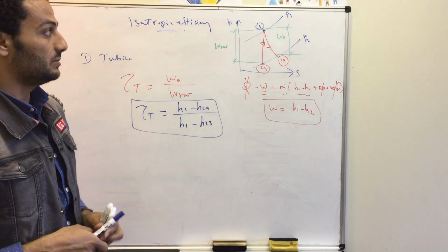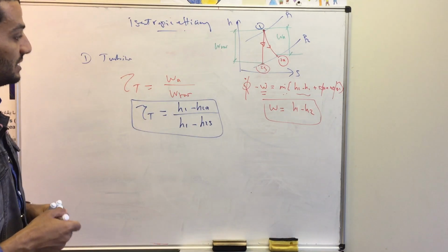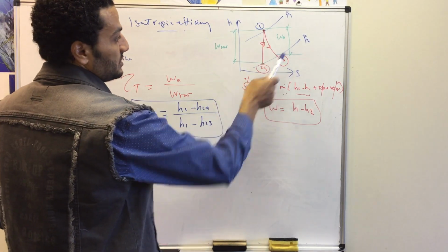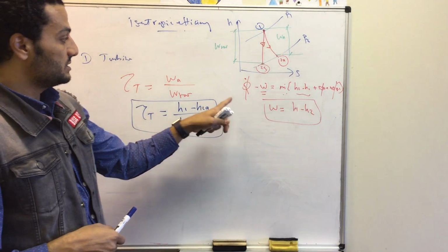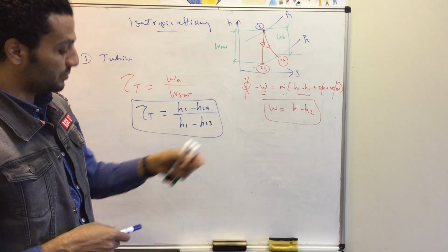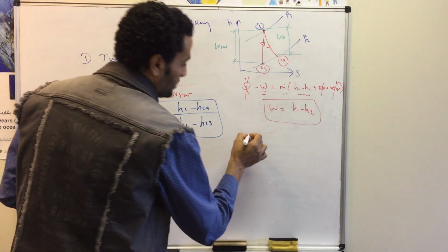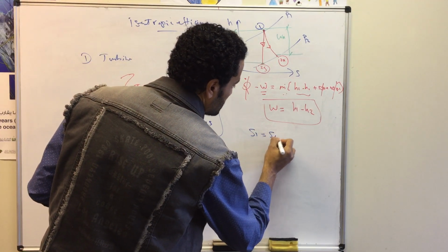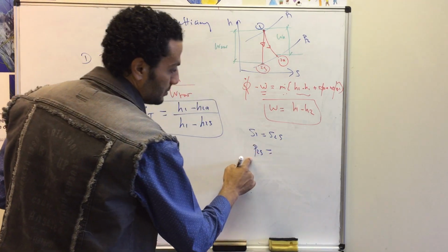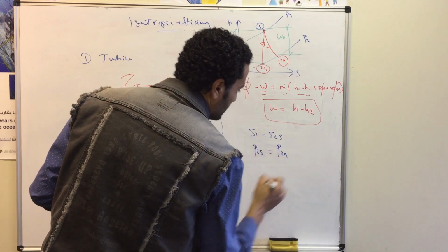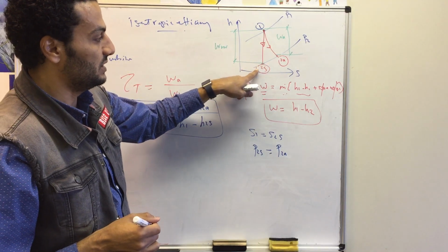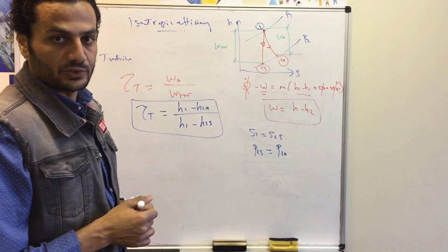Let's say we do have a steam turbine, with given pressure and temperature, then we can go to the table and calculate H1. At the exit condition, the real conditions are given, P exit and T exit, then we can calculate H2 exit. And the relation between point 1 and point 2S is that the entropy S1 is the same as S2S, and the pressure at the isentropic exit condition P2S is the same as P2 actual. So the actual pressure is the same as the isentropic pressure. The points 2 actual and 2 isentropic lie at the same exit pressure P2.